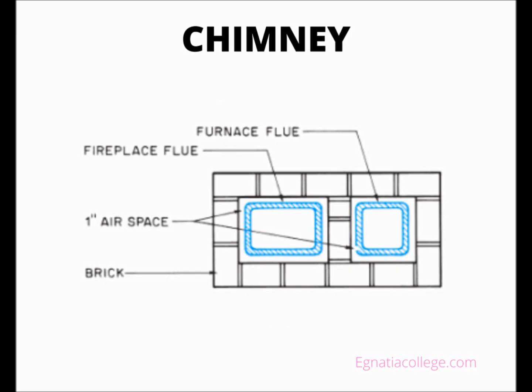Chimney. The chimney carries the smoke and hot gas from the throat to above the house. The top of the chimney must be high enough above the roof, trees, and other nearby obstructions to ensure that the air flows evenly across its top. According to the International Residential Code, the chimney must extend at least 2 feet through the roof and 2 feet above anything within 10 feet. However, the dimensions on the drawings should always be followed.